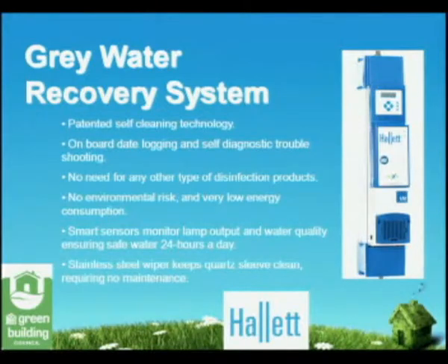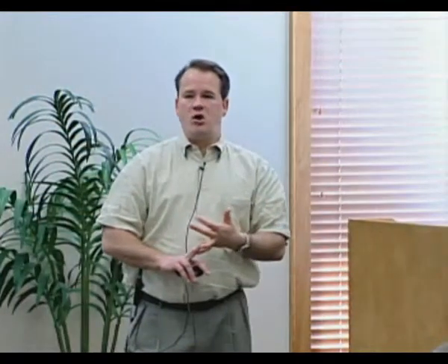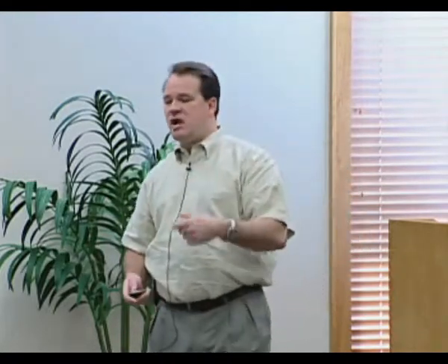And we're recycling gray water, which is basically your shower water, your vanity sinks from your bathrooms. It won't be your black water from your toilets, but we are doing the gray water. One of the things that we don't recycle in terms of the water in the home is dishwasher water or sink water. A lot of the food particles create a lot more problems for our filtration system, but using it for the vanities and the showers isn't a problem.